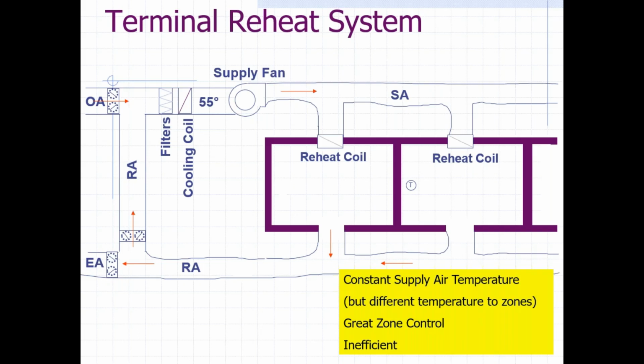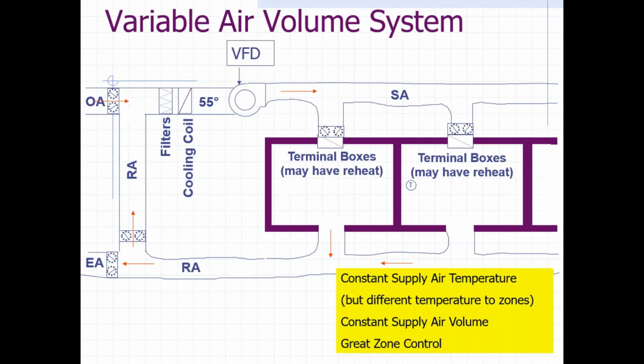So one of the main ways we try to save energy in HVAC is we try to reduce the simultaneous heating and cooling. That's why terminal reheats are not naturally 90.1 compliant, not at all. It's just not acceptable anymore. Let's move on. No one installs them.